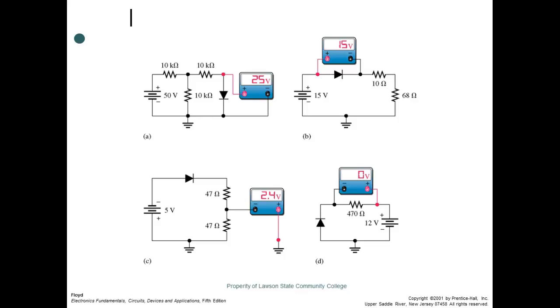But I guarantee you, this class is small. We only got 7 people on here. That question is going to be on a test. The diode is going to be reverse biased. I'm going to ask how much voltage drop across the resistor, and it's going to be 12, and somebody's going to put 11.3. Somebody in this class is going to do that. All I have to do is put that little Si up there, saying it's silicon, and for some reason that 0.7 of a volt drops in your mind, and you don't even look to see if it's what? Forward or reverse bias.